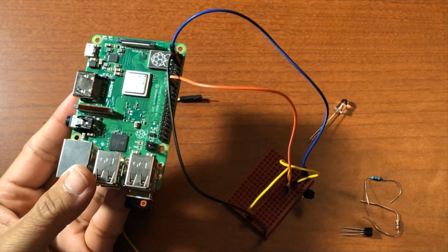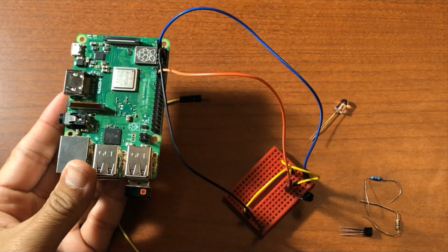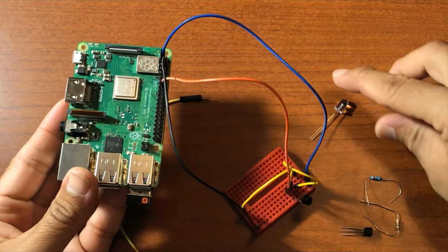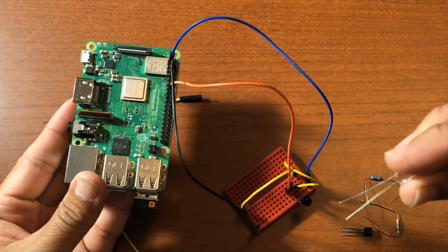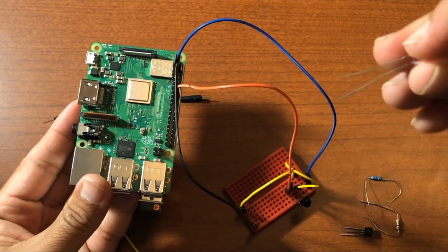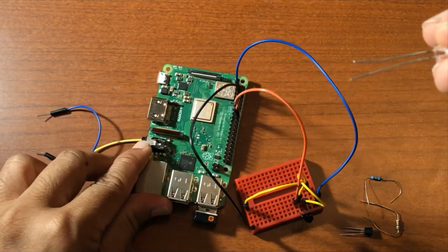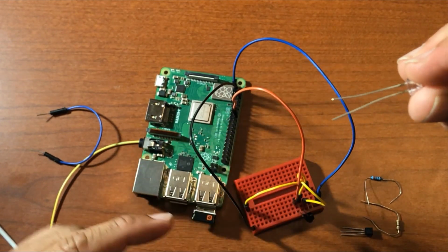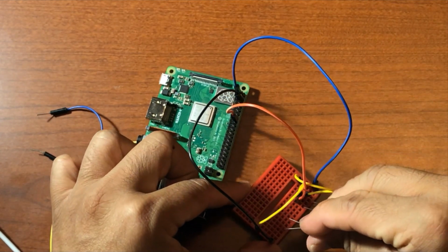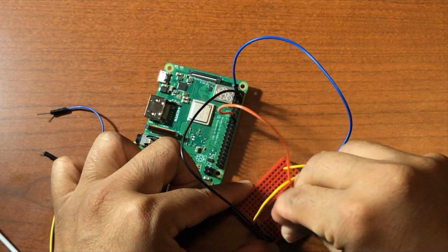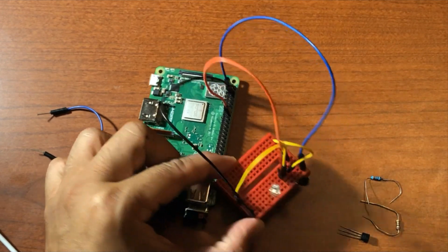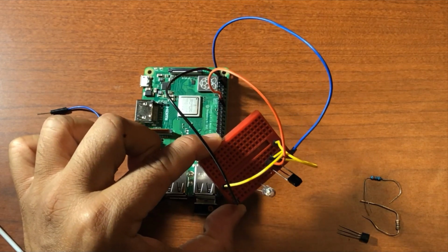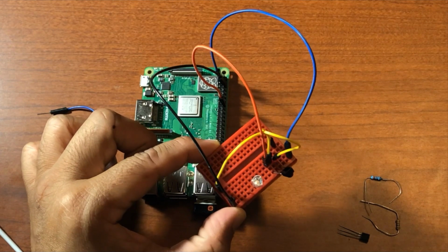So that's the wiring for the infrared receiver, and now we're going to wire up our IR LED. So here's the IR LED. We're going to put it on the circuit. Make note of the cathode and the anode. In this case, the longer pin is our anode and the shorter pin is the cathode. I'm just going to insert that into the circuit. What we want to make sure is that these are facing outward in the circuit. That way we can orient our circuit and point it to our TV when we are trying to emit the infrared signals.